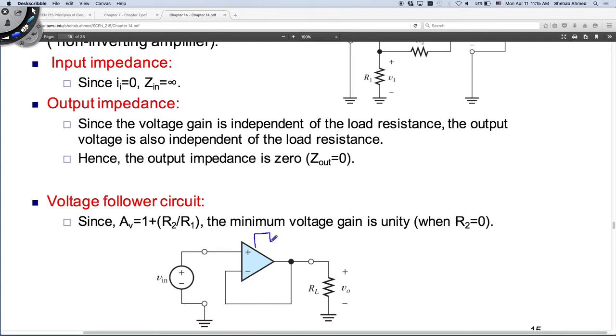Remember, the op-amp is supplied by a power supply. It has a power supply that is supplying this current. Remember, there's a voltage source inside this op-amp. So the current that is flowing in the output is not due to the input at all. The input current is limited by the input impedance, which is very high. So very little current is coming, actually ideally it's open circuit. This is an open circuit terminal, right? So there's no current coming from your sensor.